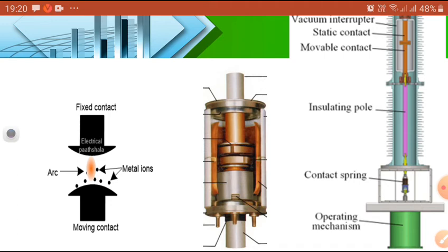When current density increases at these points, resistive heating takes place. In heaters, we know that whenever current passes through resistive materials, which have a small amount of resistance, heat develops. Here heavy short circuit current flows through this, so it is known as resistive heating.